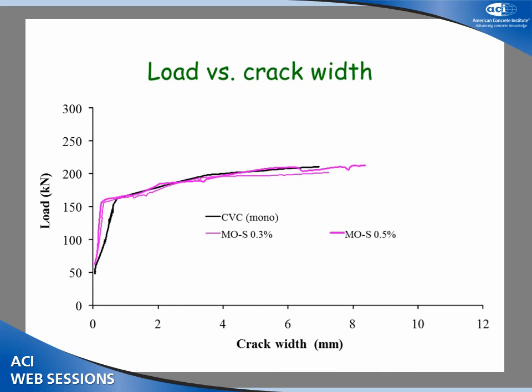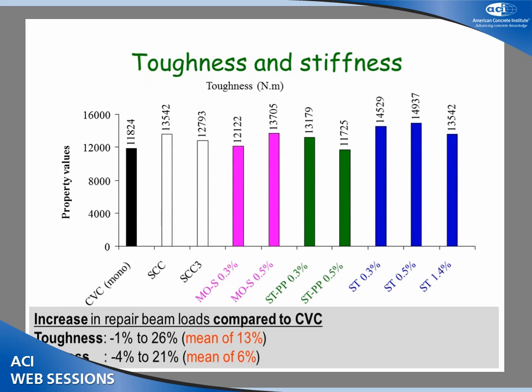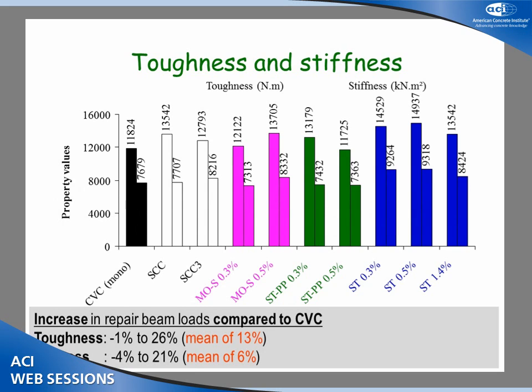The crack width is very important. So we have here the conventional concrete, the crack opening in the tension zone versus load, and those was using fibers, synthetic, steel, the hybrid, and the sections that are even reinforced with more fibers with the mortar. So the use of the fiber is reducing the crack widths and allowing higher loads for a certain crack width. And then using these graphs, you can start looking at toughness and stiffness responses. And then again, all the fibers are giving us very similar load deflection, very similar energy that is needed to crack the concrete.